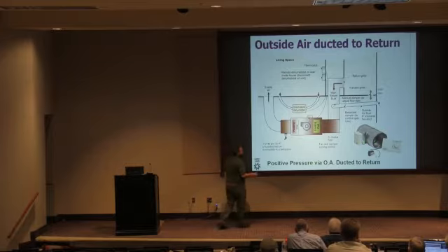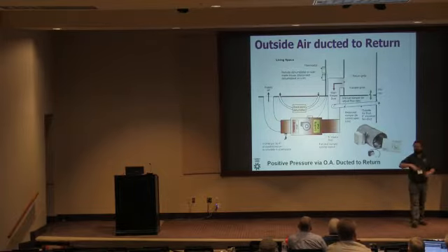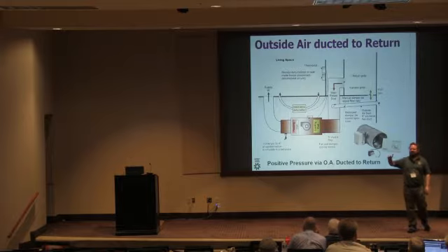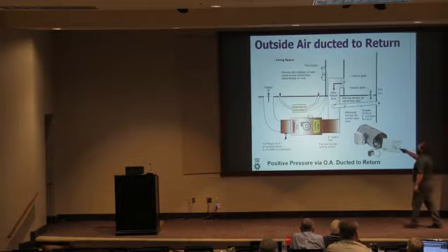It has a motorized damper, and it has a control, often called an air cycler, that determines basically how many minutes of the hour that damper is open. What this system does is it looks at the air handler with this controller, and if you're in the middle of the summer and you're getting lots of runtime on your system, then it just watches the system and says, okay, every 15 minutes or 20 minutes or 30 minutes of the hour, whatever you have the timer set for, I'm going to open up this damper and allow the system to pull return air from the house.